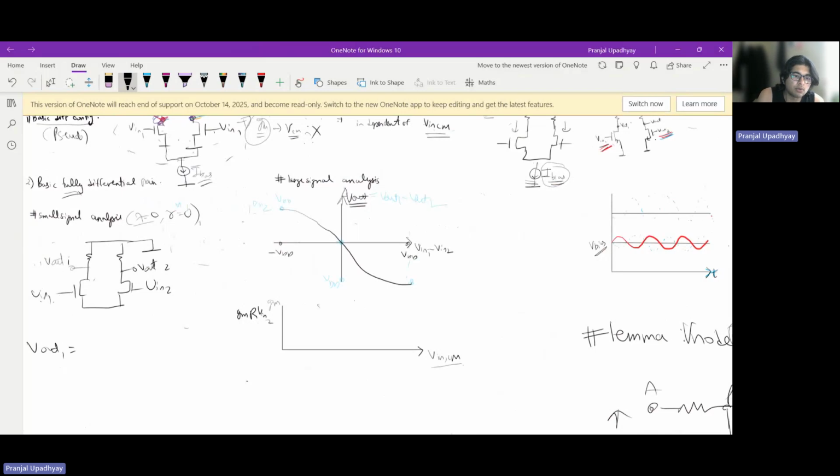So now due to this input, if you try to see what will be the signal here due to Vin1, I think we can already imagine that this is just a CS stage, and we have to just find what is the resistance looking through this path, right? And through this path, we already know from our previous revisions also that the impedance is 1/gm.